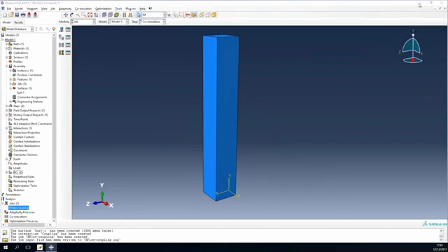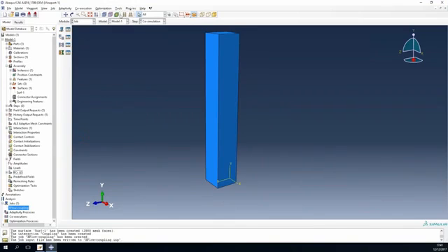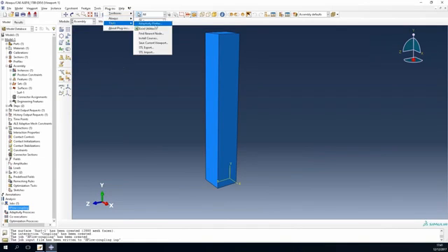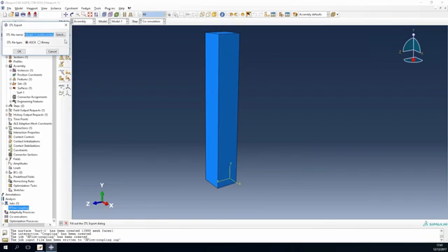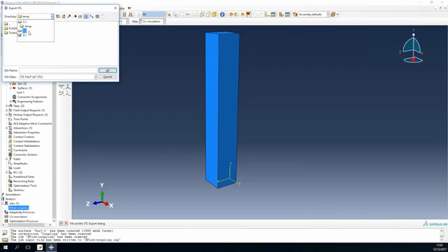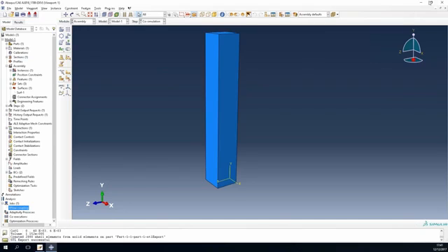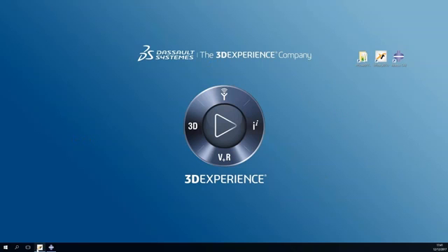So that's set, and probably the last step is to export this geometry. So let me do that quickly. You have in plugins, tools, STL export. I'm going to export the geometry as an STL file, so then I can read that into XFlow, and then I can use that to specify where the bar is going to be. Okay, so let's do that live, and let's call that bar. Perfect. So that's my export of the geometry completed, and now I'll do the setup in XFlow.